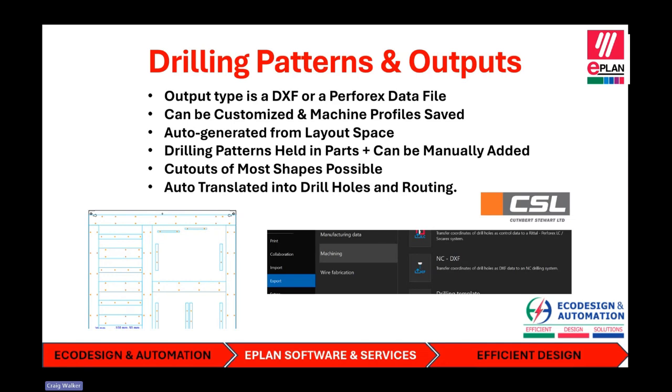So when you've completed your panel, you can output, say, a DXF file for either a Perforex machine from Rittal, or there's other formats you can export that will allow you to use nearly any laser cutter or digital drilling and machining tapping machine to produce automated panel cutouts. You can customize machine profiles and save them for different machines, or say the different couple of suppliers that'll do your cutting out. You can save their machine profiles or what file output setup works for them within ProPanel.